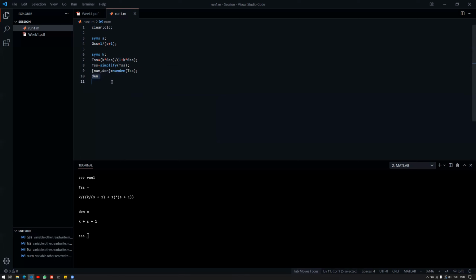So at this exact same point, I can choose between two separate approaches. One of them is to use the coefficients of this polynomial in order to calculate what the poles are. And the other one is to equate this to 0, solve for s, and then plug in k, so I get again the positions of the poles. So let's for now use the coefficient method. So let me try to calculate the coefficients of the denominator.